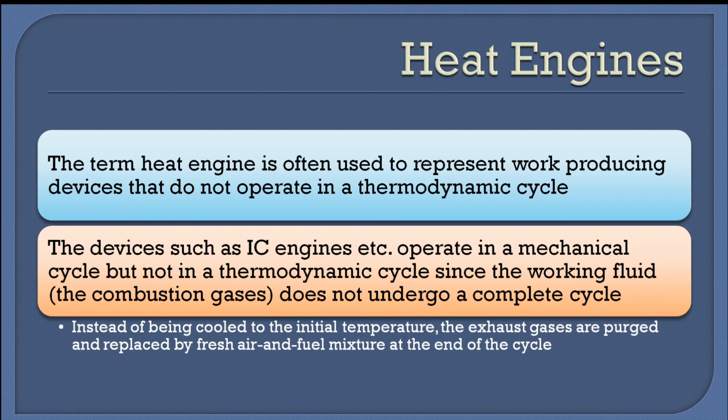I hope you know the difference between thermodynamic and mechanical cycle in detail. So please understand the difference. It is not a thermodynamic cycle since the working fluid does not undergo a complete cycle. As I mentioned, there will be replenishment of the working fluid at the end of each cycle in the case of a mechanical cycle. But in the case of a thermodynamic cycle, it will be a closed cycle. The same amount of working fluid will be undergoing the different processes continuously.